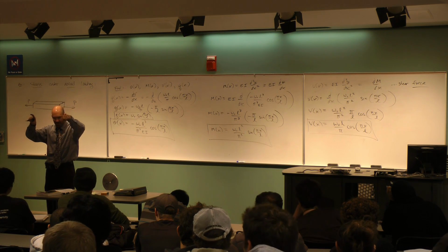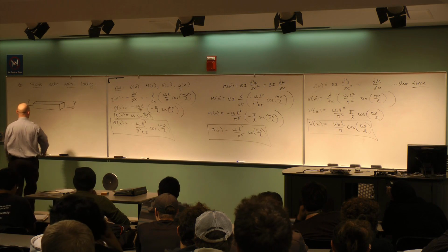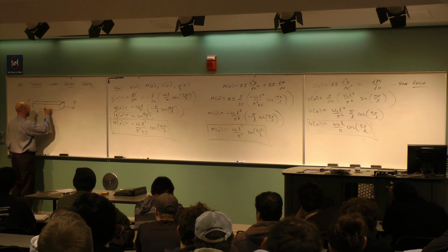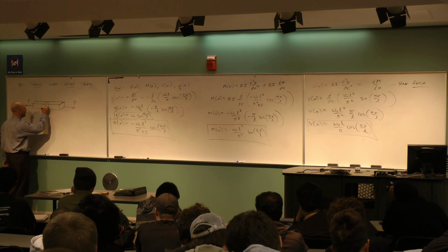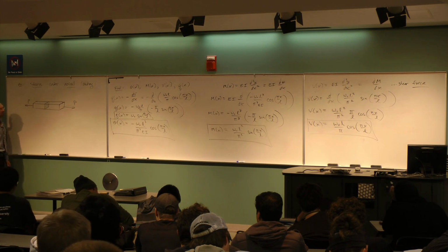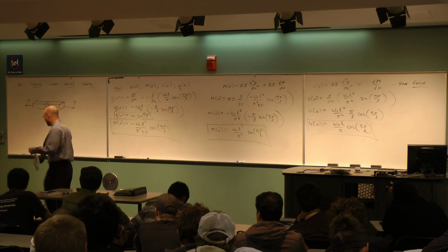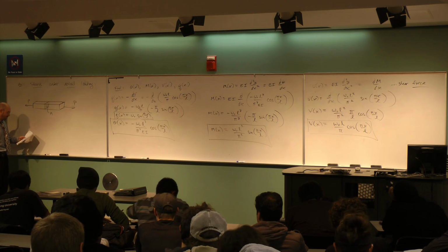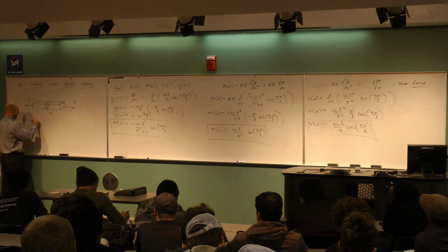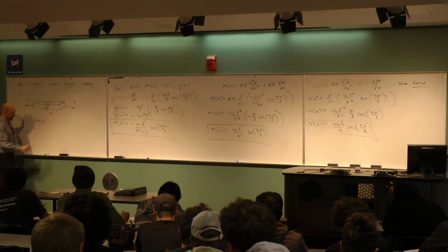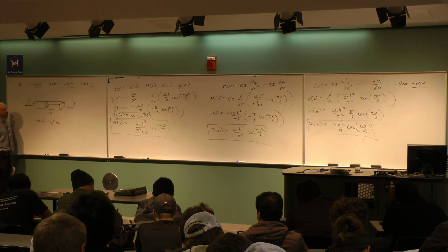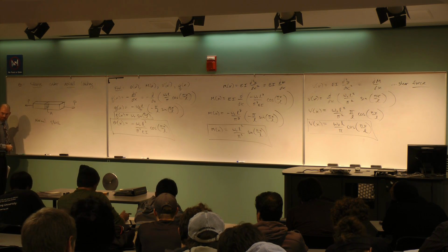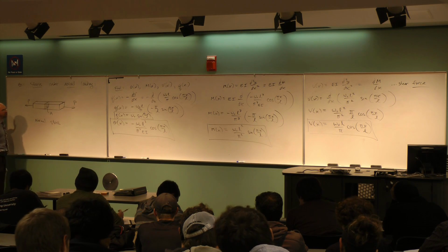Thickness to me is this dimension. It's probably the width, right? So isn't it true that to break this, it's not really how big is the load, it's how much load do I have that acts on the cross-section of the material, right? So inside this thing, the cross-sectional area is what is having to resist that load. Okay, and so this cross-sectional area inside the material now is what I'm going to call A. Okay. So it turns out what breaks things is actually values of stress. Okay, and normal stress is the stress that occurs when I load something axially. Normal means perpendicular. That's what the word normal means. Okay, so stress perpendicular to the cross-section.